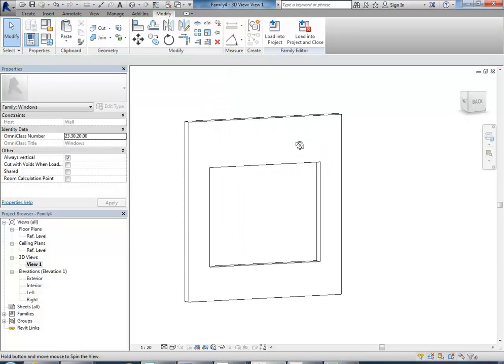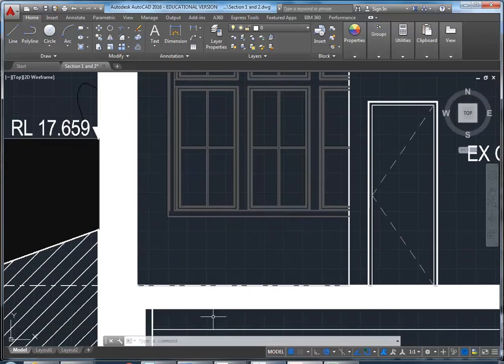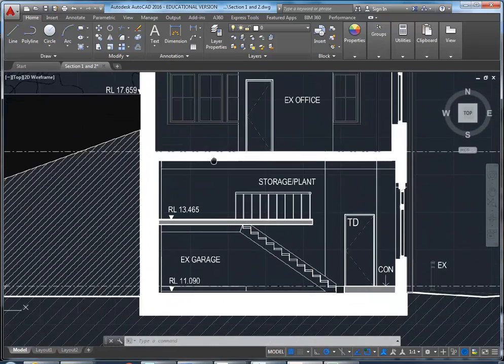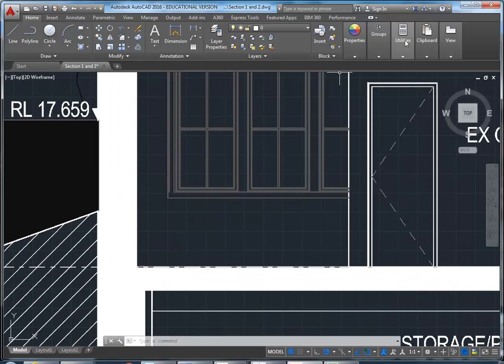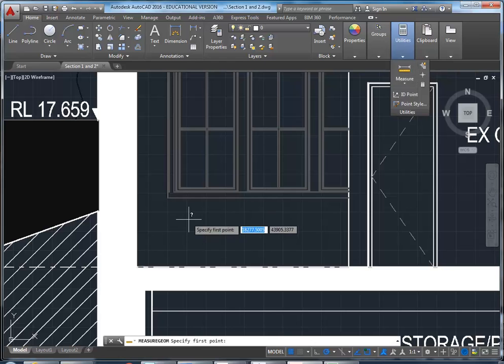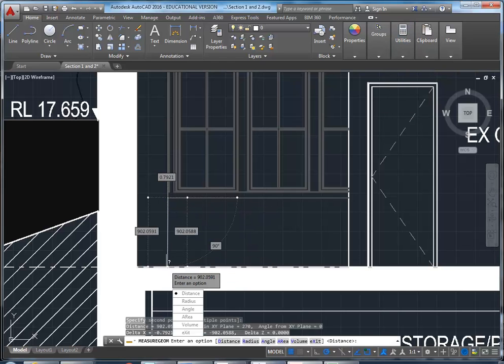So that's a good starting point to then do some modelling, but I also want to get the sill height. Here, unfortunately, we don't have any windows on the lower level, but we should be able to measure the sill on the drawing we have here for the upper level windows at least. So that's 900, that's pretty typical.